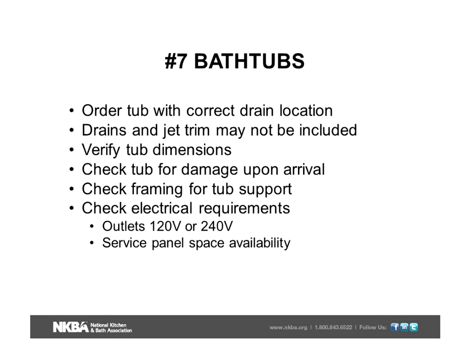Bathtubs. When we get into bathtubs, some points that were made from the people supplying me with information. Order the tub with the correct drain location. We get so focused sometimes on making sure we have the right color, the right finishes, and the right style that we forget to specify left or right. Very simple mistake. And if it comes in the wrong place, it's going to be a very expensive and time-consuming project to get it back again, particularly if it was special order.